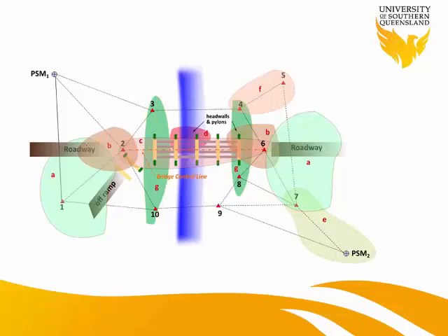So we identify the areas. Area A basically represents the road surveys for the approaches and off-ramp. You see, there's an off-ramp, there's a roadway. Then there is a B section that has different accuracy, which represents the major earthwork on the approaches. So they might require different accuracy. Then we have C, which is the bridge control line, needed in terms of alignment and distances. Accuracy requirement is very precise. And then we have D area, which is the head walls and pylons, where we want to do girder installation plus final checking for all of those.